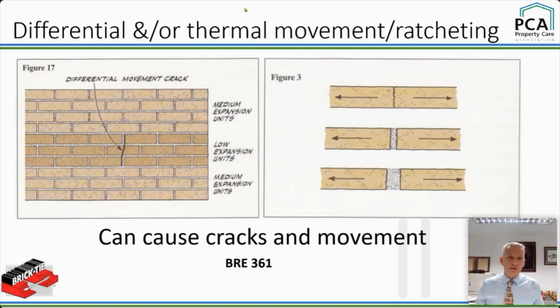So there you are on the left-hand side: thermal movements, but differential materials. So you get cracks in certain bodies of the wall. This is what I like to think of as unsightly nuisance cracks, not structural problems. If you leave them alone, the right-hand figure, figure 3 as it's labelled in the book, shows you what can happen, because you get a hairline crack as it relaxes.